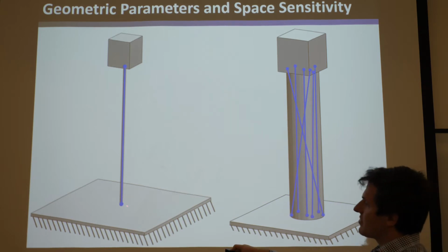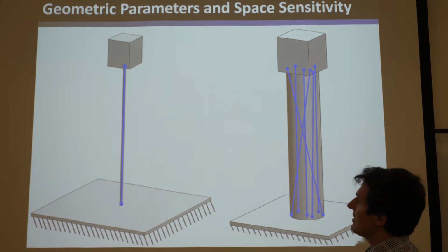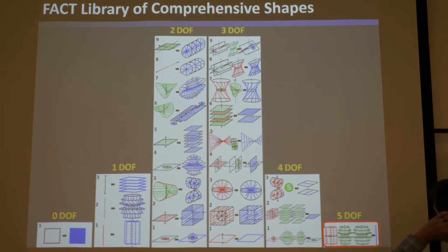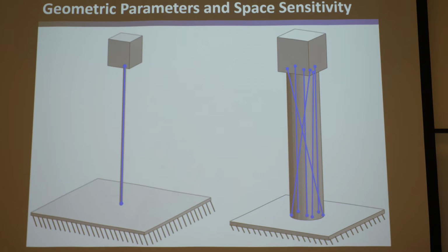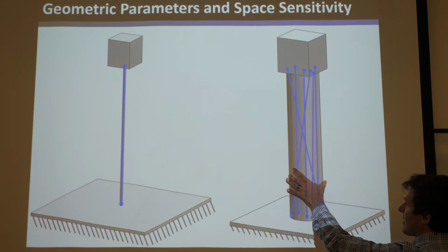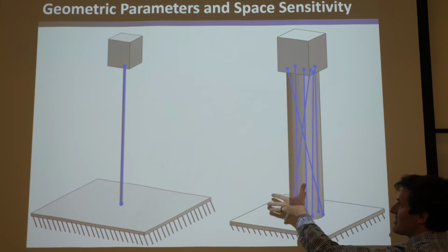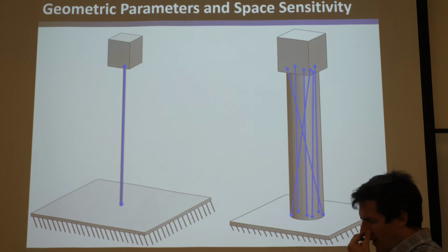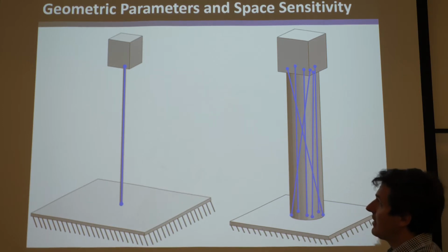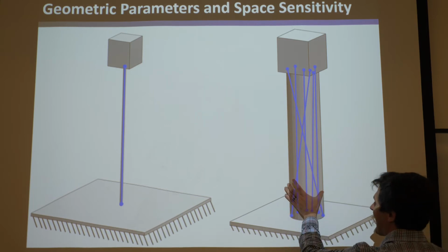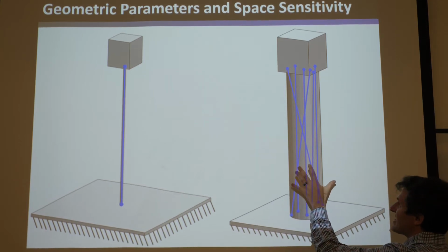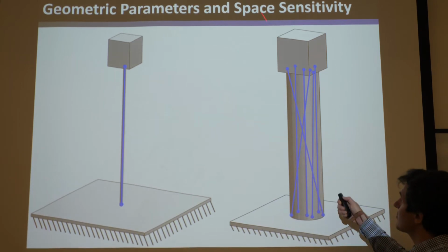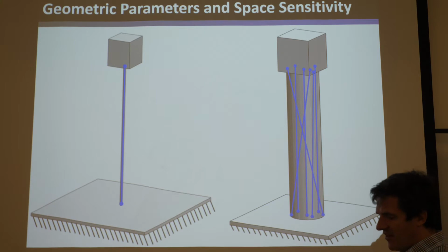But if you look at this, you think, well, there's only one blue line that fits in it, and so its constraint space is here, and therefore its degree of freedom is here. So then the question becomes, as I shrink this diameter, at what point does it suddenly transition from no degrees of freedom to 5 degrees of freedom? Okay, and according to math, if you just want to be super strict with math, then at all finite diameters, this has no degrees of freedom. You can draw 6 independent blue lines and an infinite number of redundant blue lines.